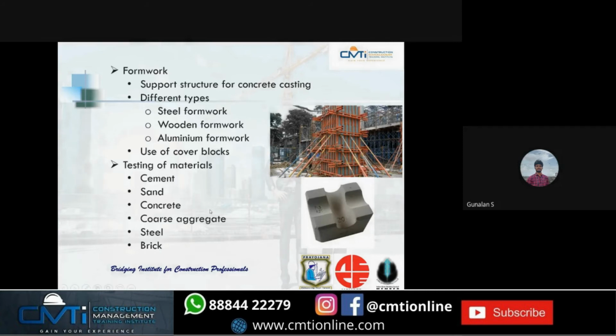For concrete, we have a crushing test, compaction test, and slump test, especially, which is done in the field. For coarse aggregate, we have specific gravity test, then crushing test, impact test, etc. For steel, we have tensile test and bending test. For brick, we have water absorption test and crushing test, etc.